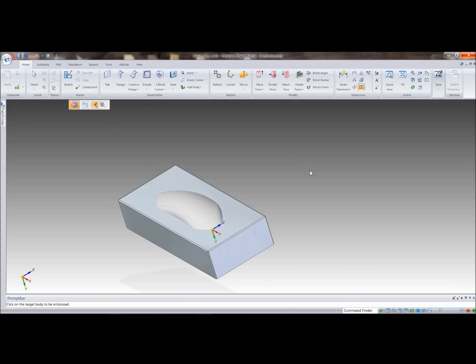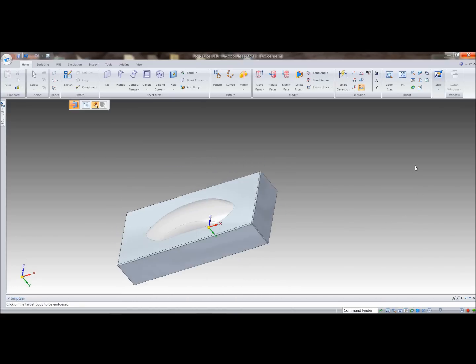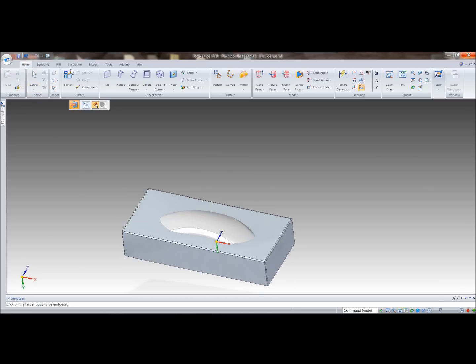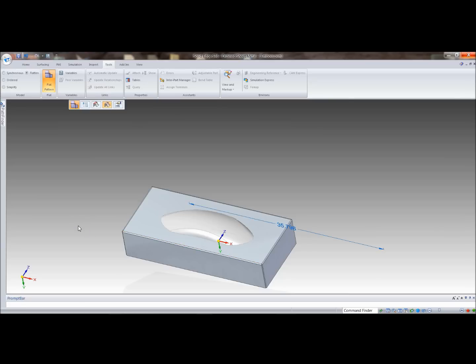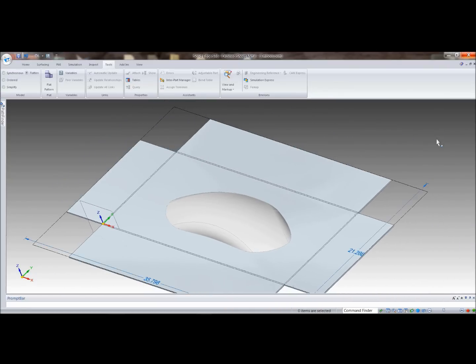just as you would think, it has created an emboss on top of that box, or that box shape has taken on that embossing. And even if you flatten it, that embossing will stay there, and then you've got some locations for the tool to stamp that into the sheet metal part. So again, embossing, nice, very nice function that they've made available for us in Solid Edge ST6.